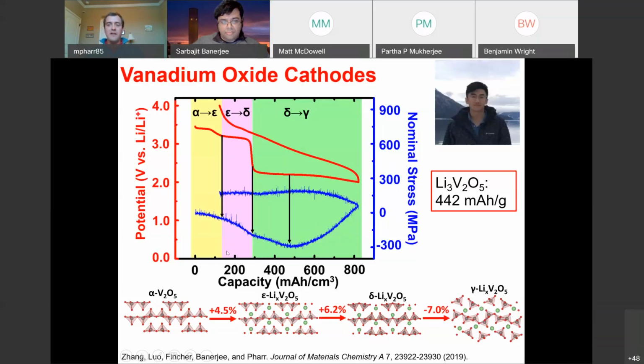But in this highly constrained system that we've developed for these thin film batteries here, and going to deep discharge, basically, when we then delithiate, you see this thing's relatively flat. We end up with residual stress, and we end up getting damage in the system after just a few cycles. And so this tells us about what are intrinsic sort of stress levels associated with the lithiation of V2O5 itself. But how can we mitigate this issue?